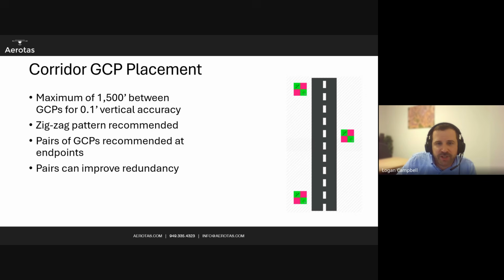Even on sites with little vegetation? The answer to that is, on a site with little vegetation, I would recommend using photogrammetry instead of the LiDAR sensor at all. If you are doing a site on a hardscape, photogrammetry remains cheaper, more accurate, and can actually give a better visual picture. When you do have sites with vegetation, though, yes, we always recommend penta-return or triple if you're on